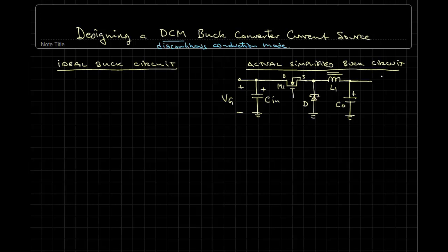Electrolytic capacitor for providing significant energy storage, bulk capacitance, but then also some smaller, perhaps ceramic capacitors in parallel, which have lower series inductance and behave as a capacitor up to much higher frequencies, where an electrolytic capacitor will cease behaving as a capacitor and will start to act more like an inductor because of the effective parasitic ESL, effective series inductance, that is inherent to all capacitors, but is certainly going to be much higher for electrolytic capacitors.